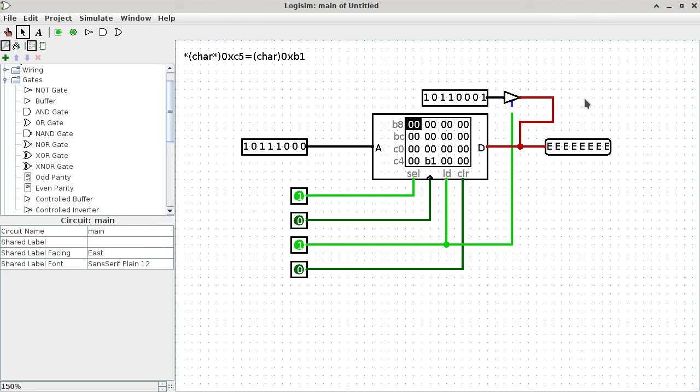So the control pin needs a 1 in order for the buffer to screen whatever it's receiving. But the LD needs to be a 1 in order to have a read cycle. It's the read cycle that is causing the conflict. So that means when the LD is a 1, we have a problem, because the input pin may not agree with whatever the data pin is trying to specify with the RAM. So we need an inverter. We need the opposite of what LD is saying.